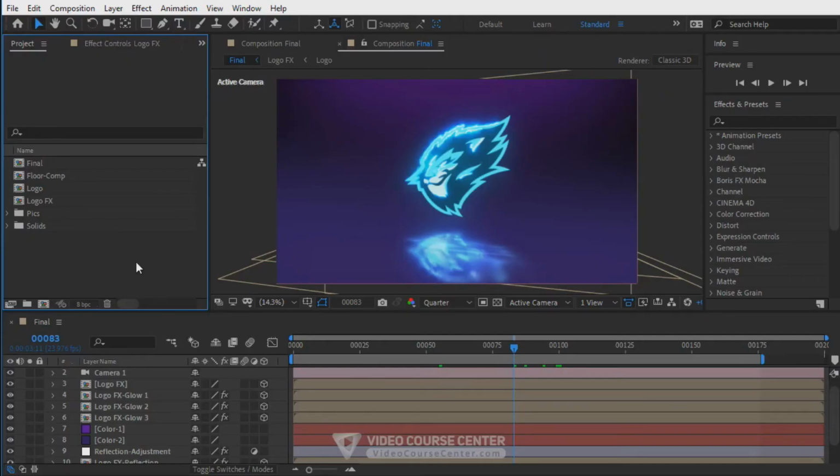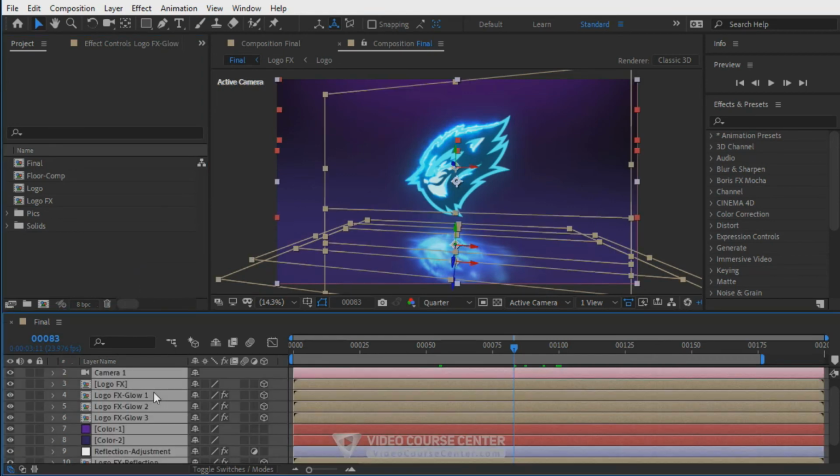Hello and welcome back. I hope you have enjoyed watching this course so far. In this video, we're gonna render our lighting logo reveal animation. But before that, let's add motion blur to our layers and compositions. So select all layers using Ctrl+A shortcut keys and here activate all motion blur options. And turn on this motion blur button as well.